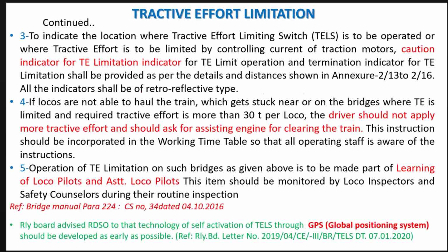If locos are not able to haul the train and get stuck near the bridges, their tractive efforts are limited; the required tractive effort is more than 30 tons. The driver should not apply more tractive efforts and should ask the assisting engine for clearing the train. Basically, it has been seen that higher tractive effort is required only while starting the loco. So it is important to see that when the train is running at normal speed, the tractive efforts